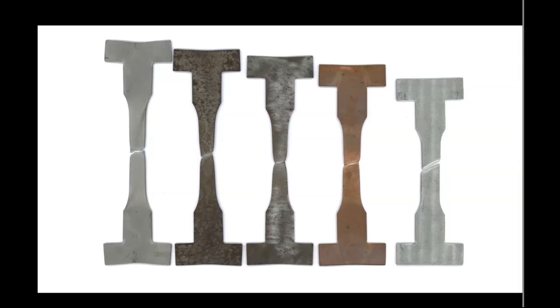If I have more defects in the pen, lines, cracks, whatever, they will allow me to use less force. This is what it actually means. So lowering yield strength. Yield is the plastic deformation. So yes, lowering yield strength, meaning weakening the material when it starts to deform plastically. So B is the correct answer.